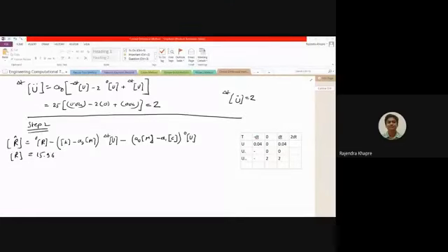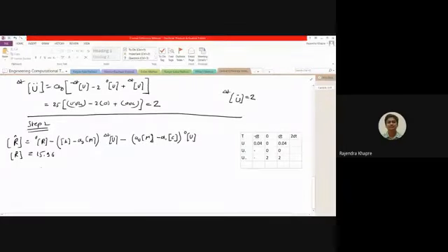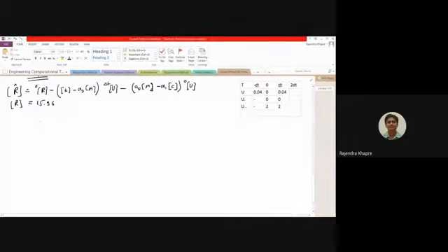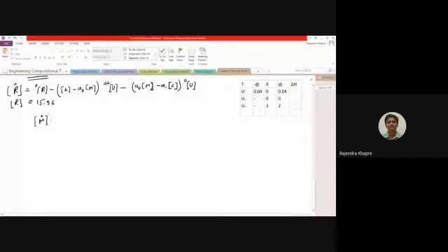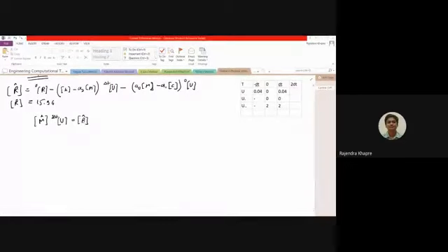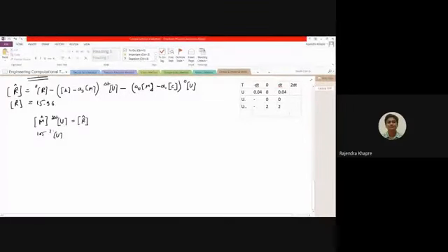Then now we have to start calculating the unknown displacement, unknown velocities, and unknown acceleration. The unknown displacement can be calculated by a simple expression. This is the effective mass matrix, which we have already calculated in the initial calculations, multiplied by u at 2 times delta t, equal to your effective load vector R. Can you do these calculations, please? This value is 105, I suppose, and u at 2 times delta t, and this R value is 15.96.